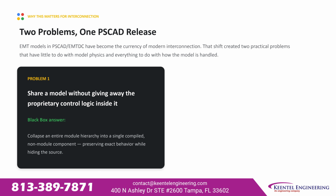Problem 1. You need to share a PSCAD model with a grid operator, a study consultant, or a third-party reviewer, but the model contains proprietary control logic you cannot hand over. The black box feature solves this by collapsing an entire module hierarchy into a single compiled non-module component. The result preserves exact simulation behavior while sealing the internals. The recipient gets a working model. They do not get the source.